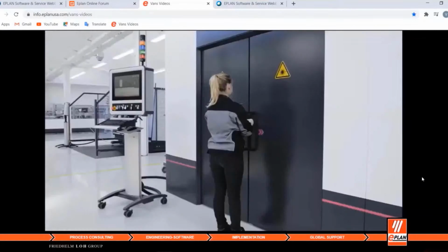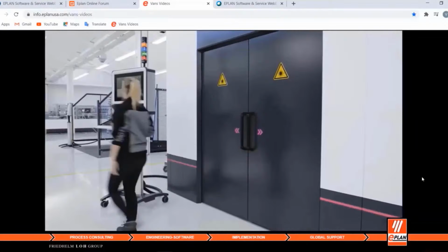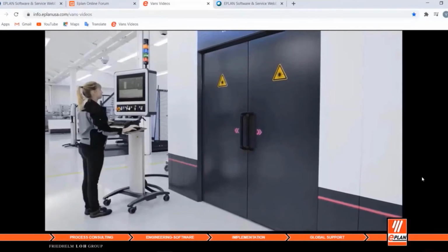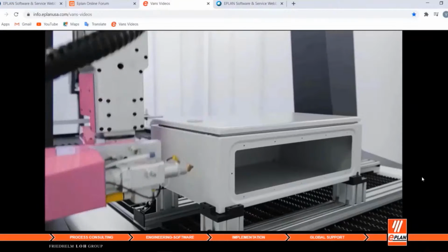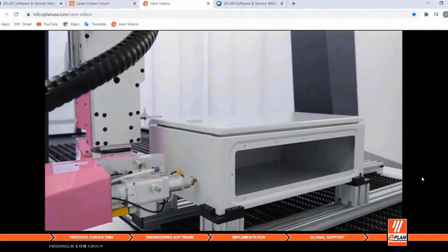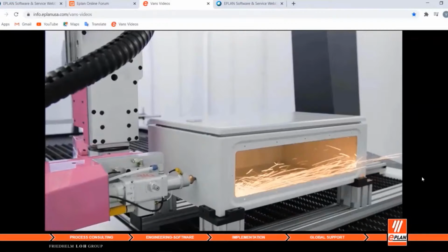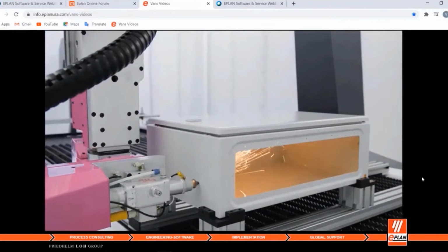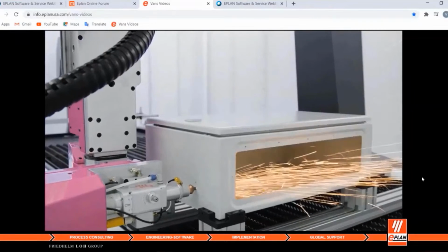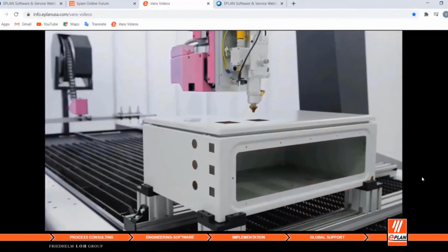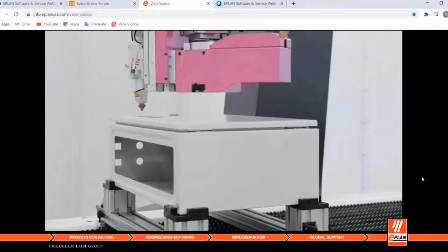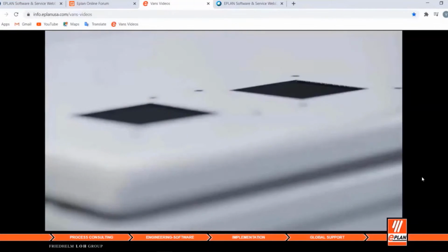It's not the fastest laser in the world, and that's not the point. I mean, all of the parameters for this machine are really set exactly to not blacken or bubble up the paint, so we're not creating so much heat like you would with other CO2 or larger fiber laser processes. But still, certainly this is much faster than doing anything by hand, and the cut quality and precision is excellent.